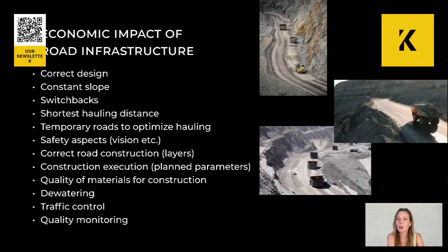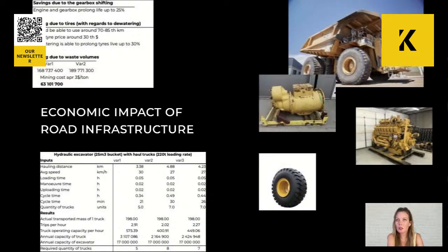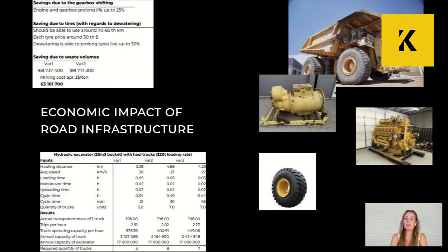And on this slide, we want to clearly show how the quarry project impacts the efficiency of using road transport. So let's revisit our 3 project options and compare the main indicators. After some simple calculations, we see that the number of vehicles required to support one excavator ranges from 5 to 8 dump trucks. Now, consider that each additional dump truck costs over $4 million, plus maintenance, plus repairs and replacement of equipment. This significant cost difference arises from the specifics of the project design.